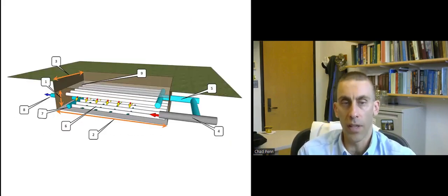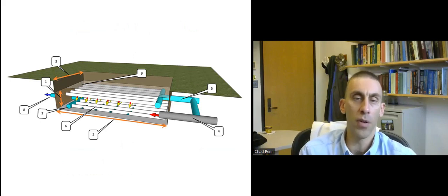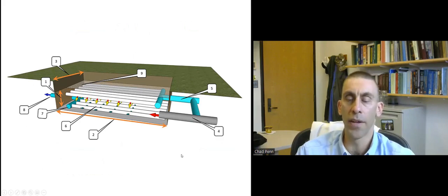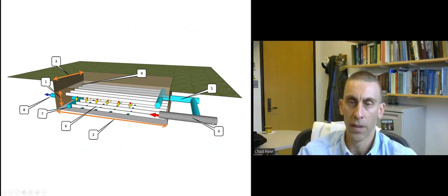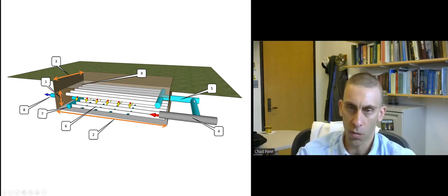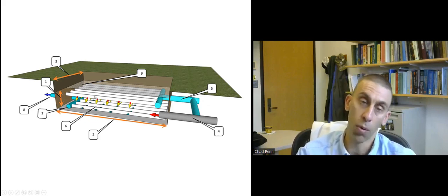This is kind of a generic look at what a lot of the bed structures look like. In this case, we're considering the context of a tile drain filter. I use that in this case because that seems to be a lot of the interest in Iowa and other places in the Midwest, but we've done a lot for surface structures as well. But if you can imagine your tile drain here, inflow pipe, water is diverted. Usually we use a flow control structure to divert the water into it. More on that later. Water flows into it, and then through a manifold of some sort, it's evenly distributed, and that's important. It needs to be evenly distributed through your bed, kind of like a septic system.